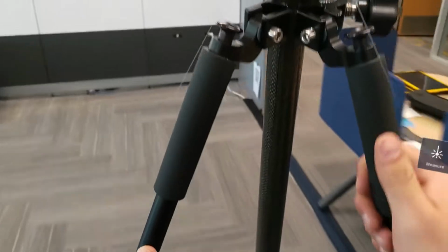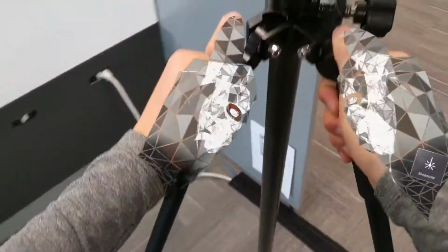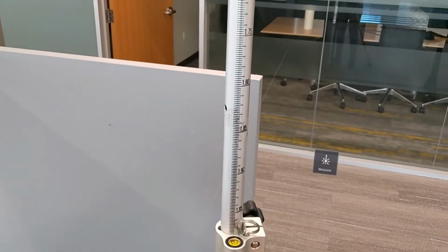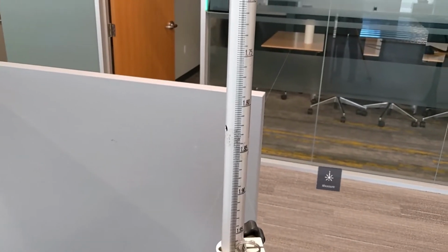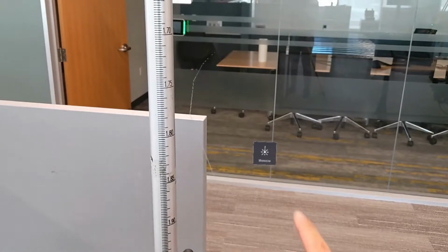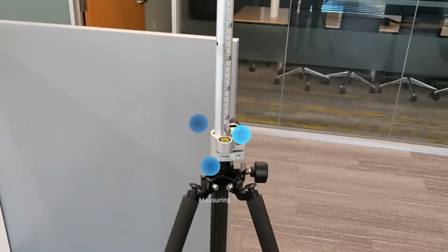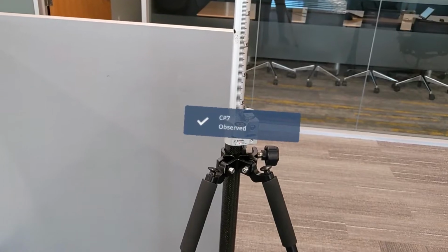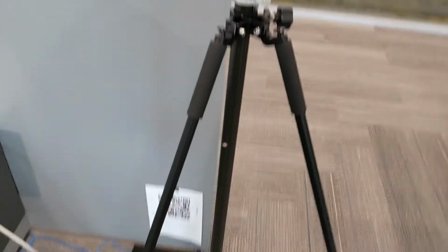In this case, we'll navigate over to our next control point. And again, position our prism pole or the laser using joystick mode and make sure that we're positioned exactly on that point. Now, I'm going to hit the measure button with my hand this time, where it'll take that total station observation. Again, confirming that I've observed it with the total station. And now I'll proceed to the alignment.